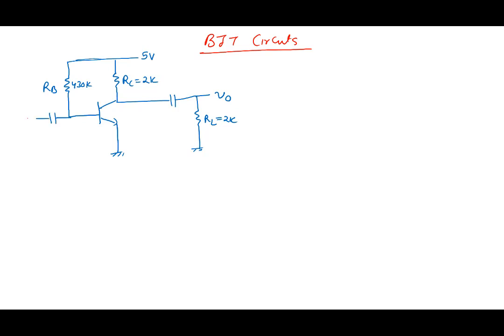Let's add an input, Vs here. So that's our circuit with some sinusoidal voltage, or a signal voltage, also applied. And let's give the transistor characteristics: beta as 100, early voltage as 100 volts, and thermal voltage VT as 26 millivolts, and that's it for the moment.